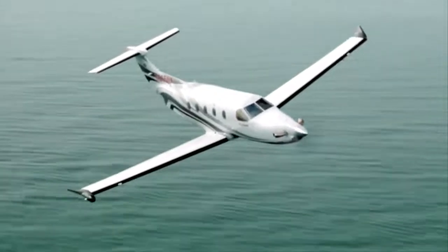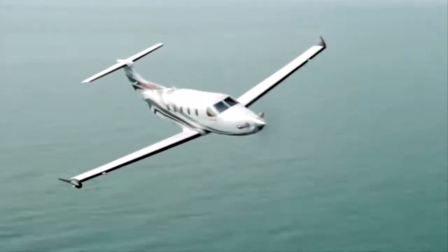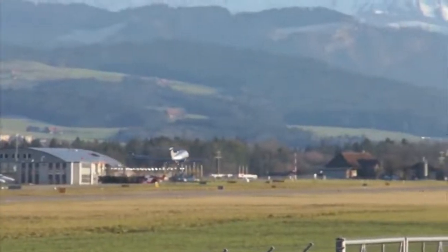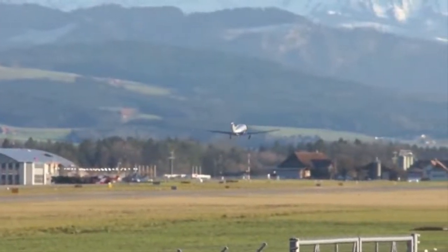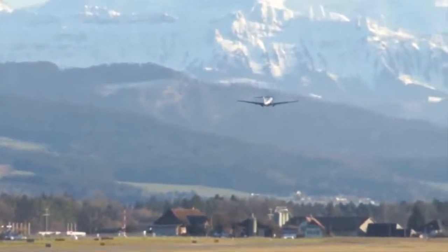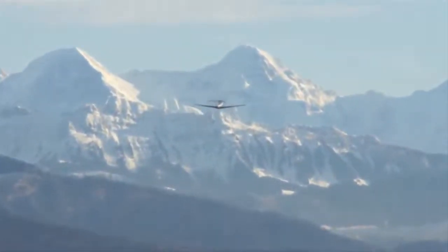RNAV approaches with LPV minimums together with SBAS systems provide an efficient alternative to traditional ILS approaches. This video has been an overview of LPV. Please be sure to refer to AC 90-107 or AMC 20-28 and your aircraft pilot manual for more detailed information.